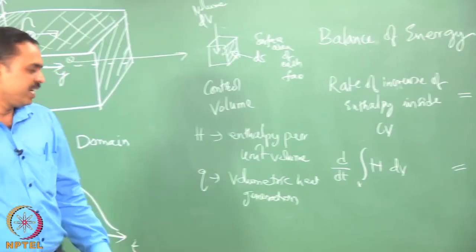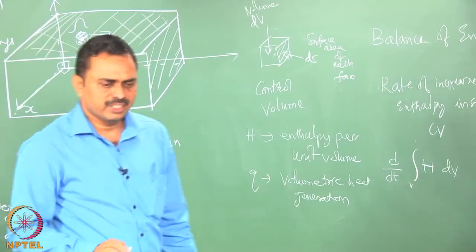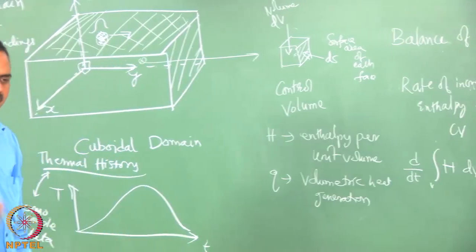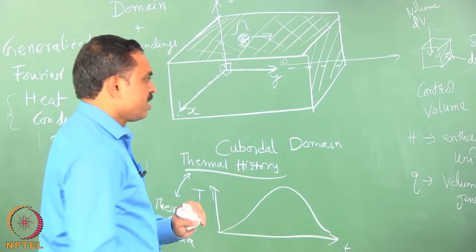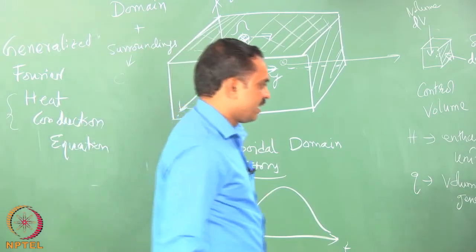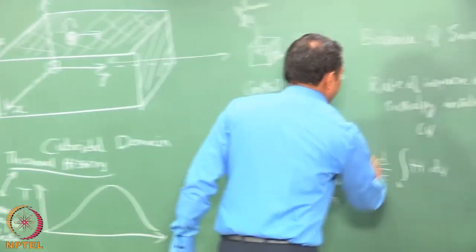Okay. So, volumetric heat generation does not exist in most welding situations, except, for example, when current is passing through the path and, because of resistance, heat is generated. Otherwise, generally that term can be neglected. Okay. So, this is the equation that we are looking at.